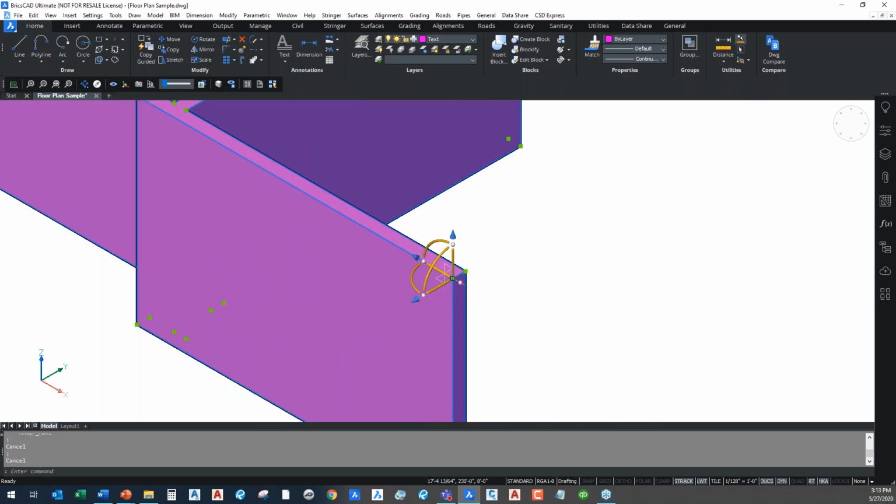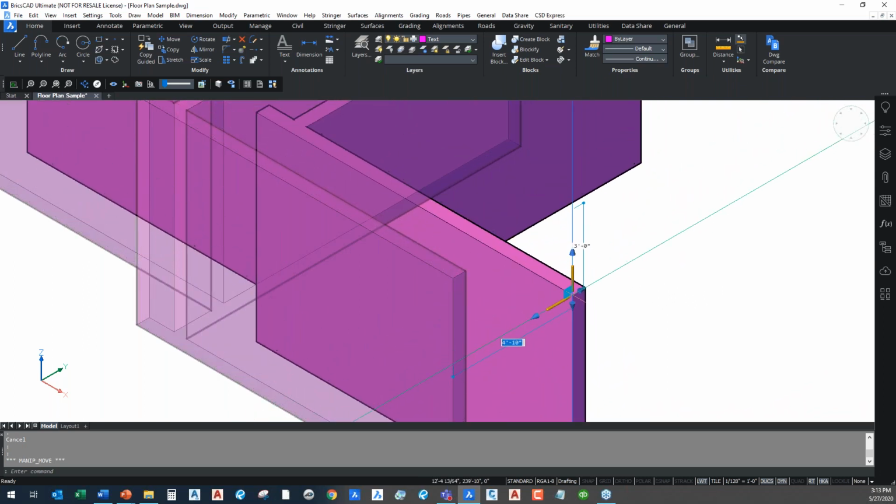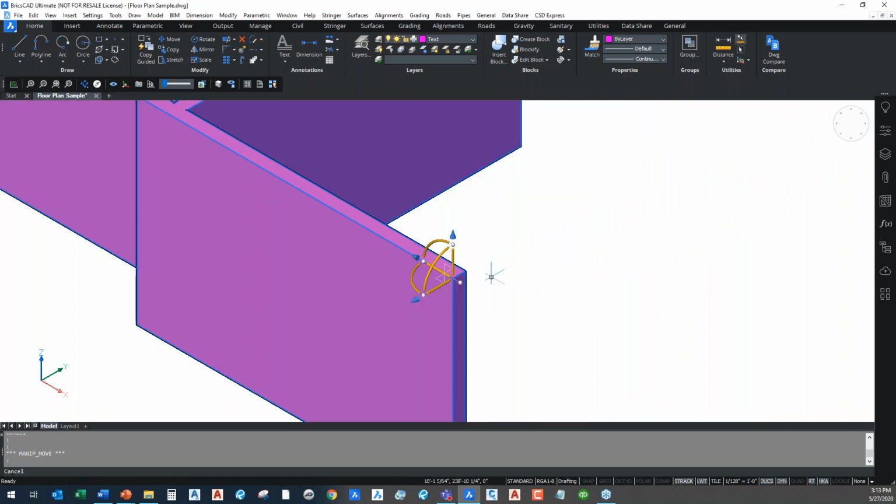Same thing, I can pick the right side plane. Now you see I can move it over and up using dimensions, using the tab key, off of that plane. I can do it off the bottom plane, the side plane, the left, the top, any of the planes. I can move over, up, over, down in either direction just by typing the correct values on any 3-dimensional object. Makes it really, really easy to manipulate and structure your buildings or whatever parts and components you're working with, okay?